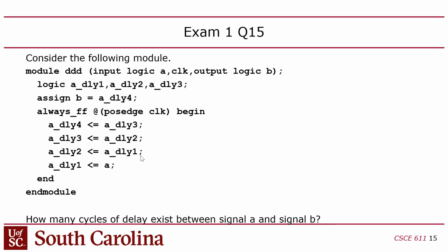Yeah, I don't understand. I thought all 4 of those blocks were in parallel with the same clock, and they would all update at the same time. They do, but inside that always, you only update these once, right? So you're going to update all these guys every cycle, and in fact, the way it's written, there's not even a data dependency here, right?